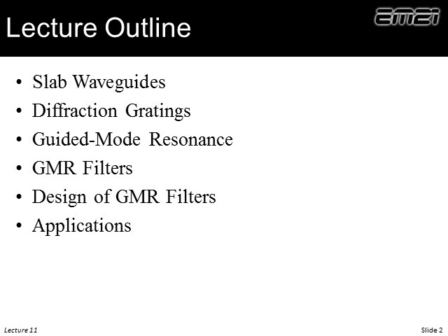In this lecture, we will learn that there are two physical mechanisms at work to produce what's called a guided mode resonance, and that is diffraction and waveguiding in a slab. So we'll talk about those, then we'll combine those concepts and talk about what guided mode resonance is, and then discuss their use as filters.